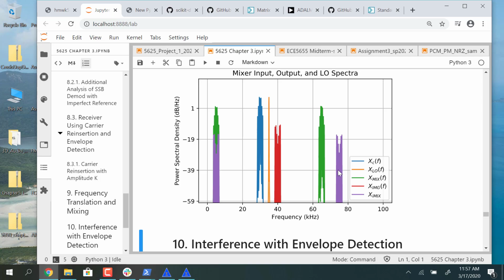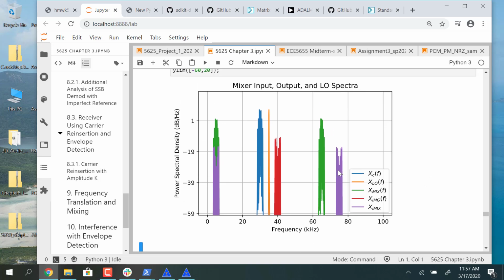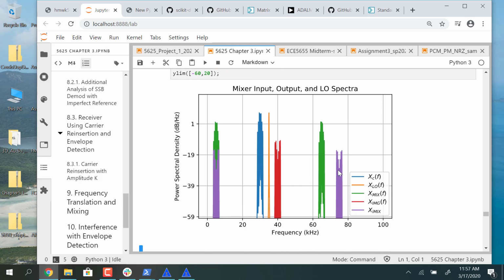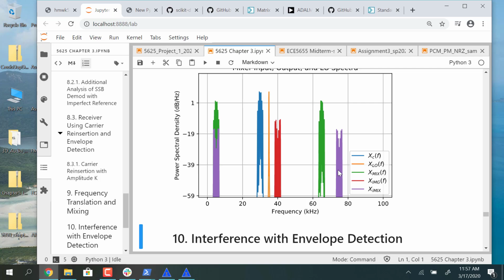So you can play around with this if you want to help understand what's going on with the basic mixing idea. The tone generation, or the multiple sinusoids, is just to create a spectrum that has width to it. So you can see that it's not just a spectral line, and distinguish between carrier pure sinusoids, which is this LO signal, and then the two modulated signals.